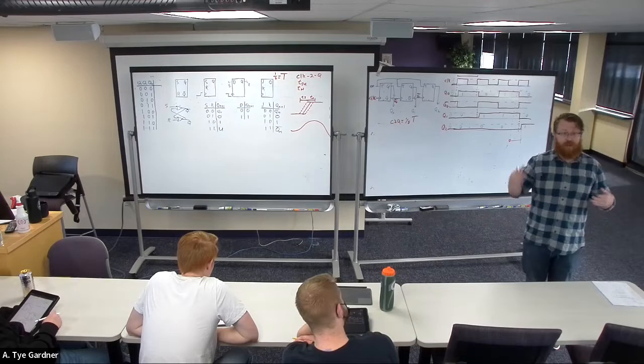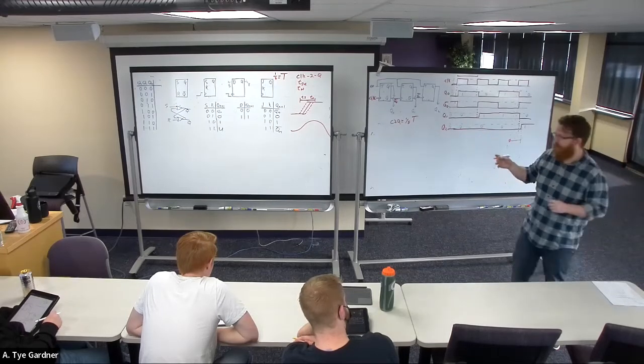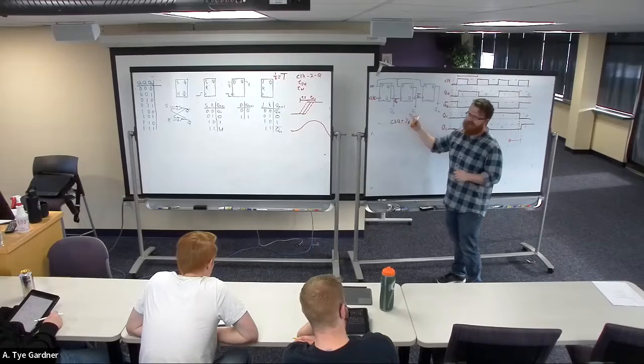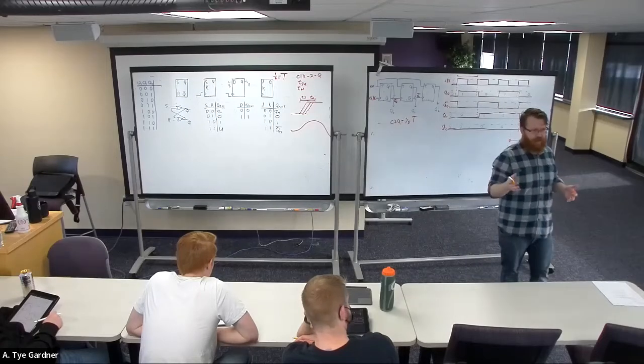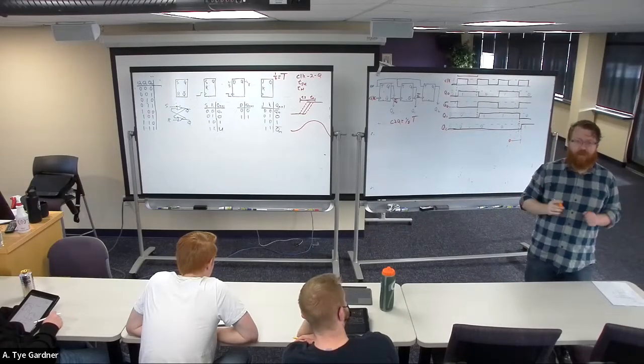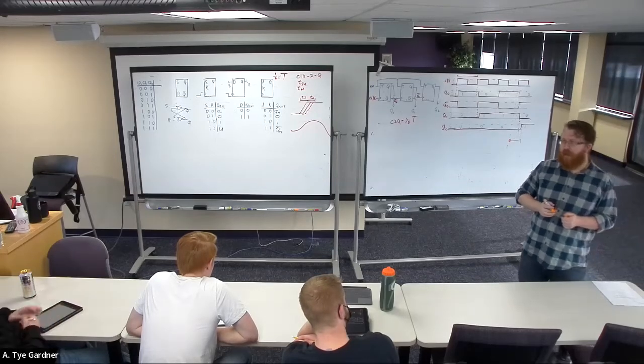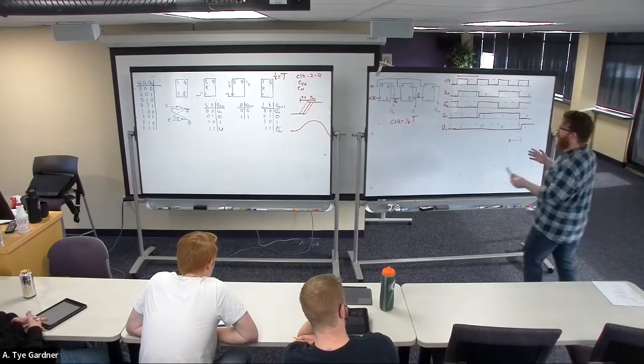So if we slow it down, we can actually end up adding more because the time will stay the same, because the devices don't really scale with the period. This is kind of just an abstraction, right? So we can slow devices down and make bigger counters, but we do have a limit on the number of bits in our counter based on the delays. Okay, and that's going to be true for a lot of things.